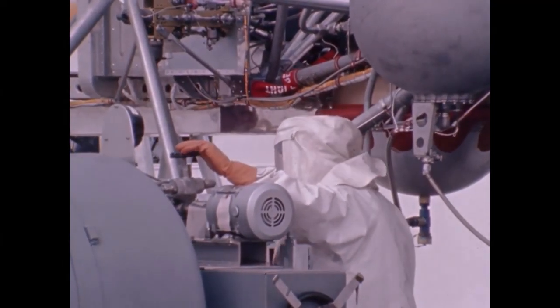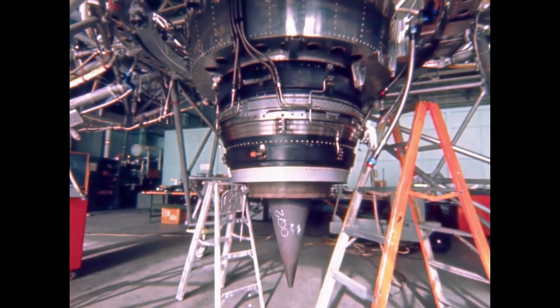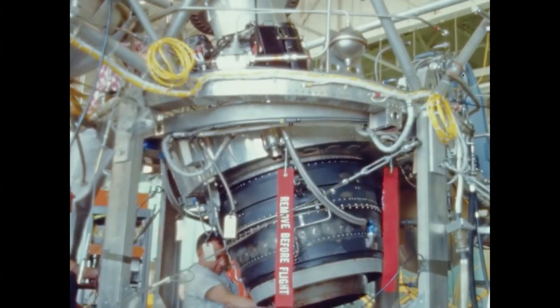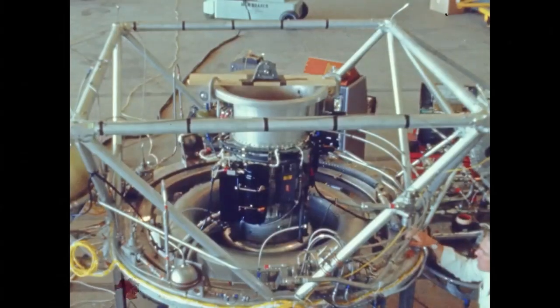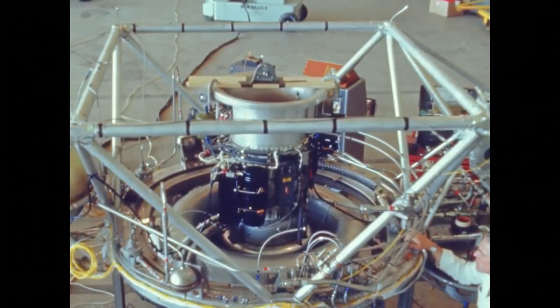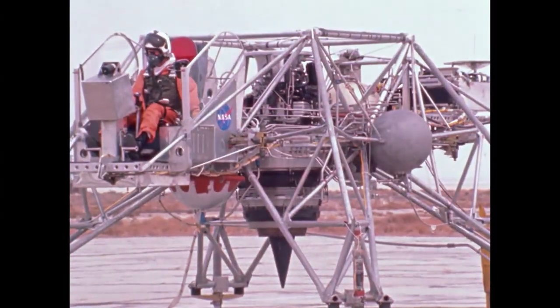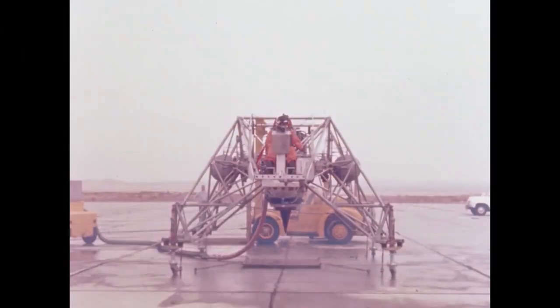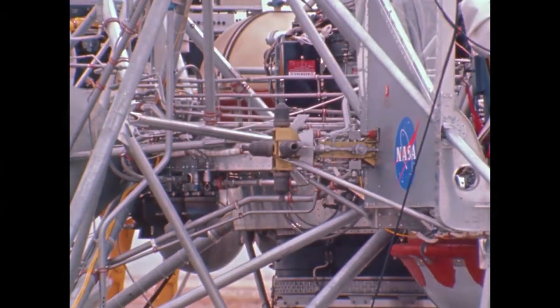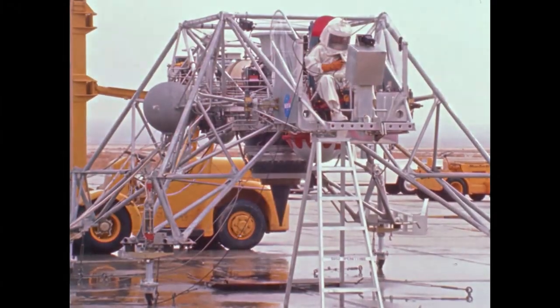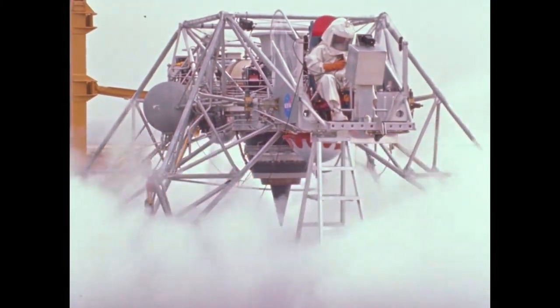The proposed method: install a jet engine underneath or within the machine on gimbals, so the thrust was always vertically upward. The engine thrust would then be adjusted so that the craft's net weight, that is its gross weight minus the engine thrust, would equal its lunar equivalent. The force required to lift the net weight would be provided by throttleable rockets.